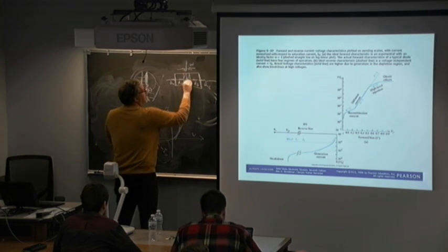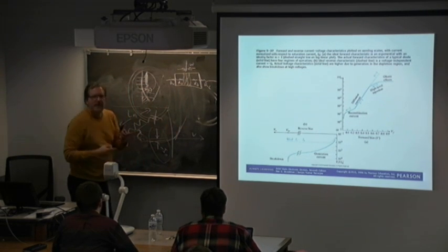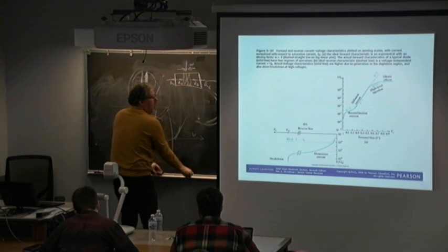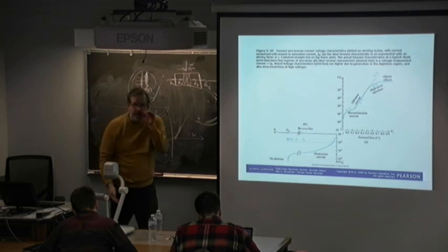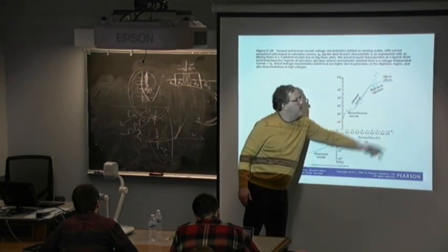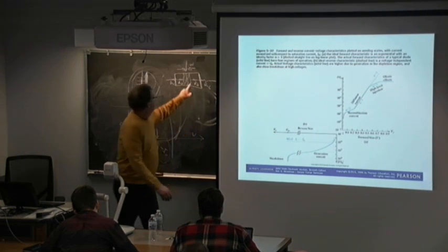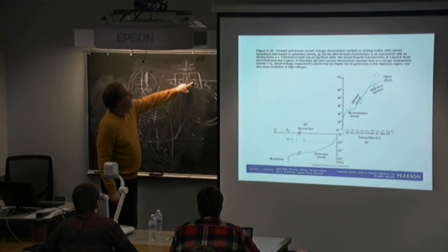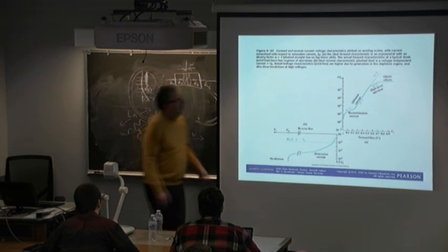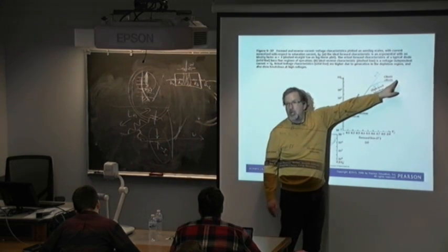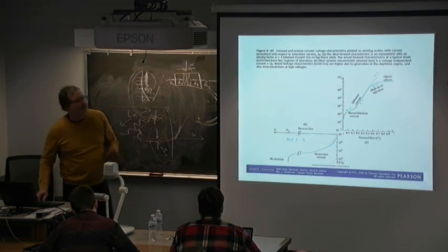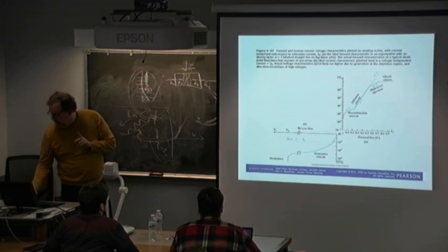And so what's happening in the diode itself is less important. It's these parasitics that are now expressing themselves more fully because the absolute current gets up and it rolls over. And with these resistances, remember, you get I squared R joule heating, so your device actually gets hot, and eventually it burns and blows up. Okay, so those are the deviations from ideality.